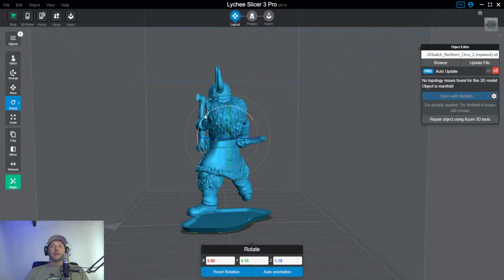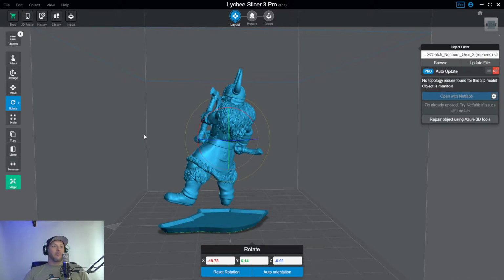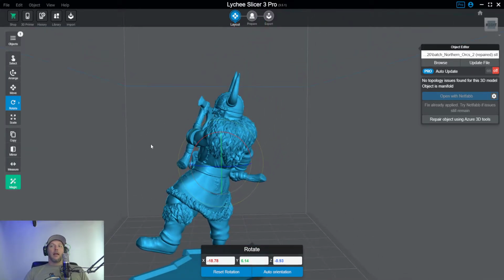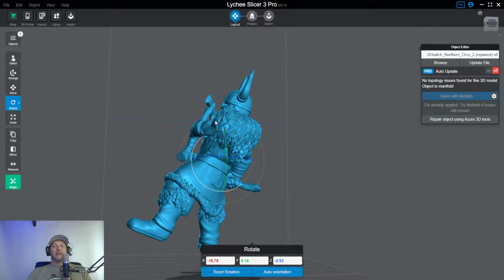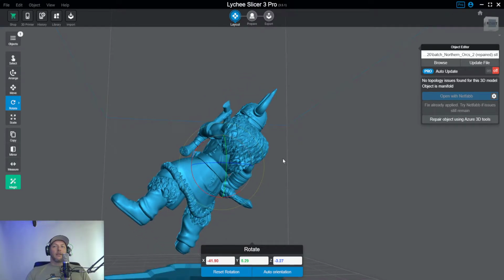There are times, let's say, for example, we like to tilt our models back a little bit, where I could have the exact same amount of work. I could adhere to priority 1. I could adhere to priority 2. I could adhere to priority 3. I can save myself a little time, or it would be an identical amount of time for me to place the supports just by tilting them a little more, right? Well, I just removed 30 minutes of print time, and all of the rest of the priorities have been maintained. So this is something to consider.